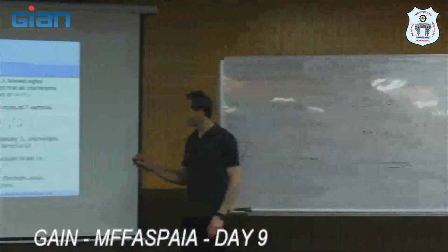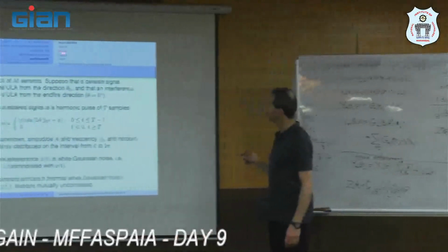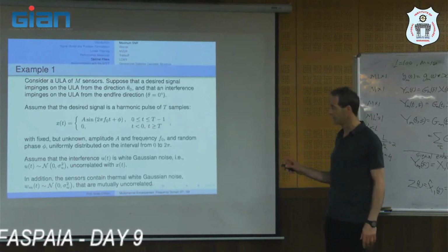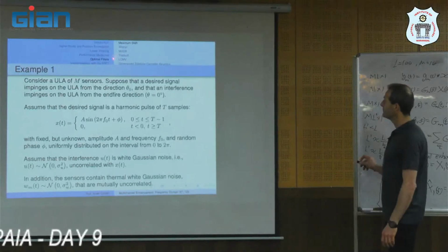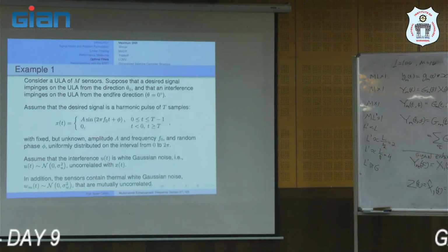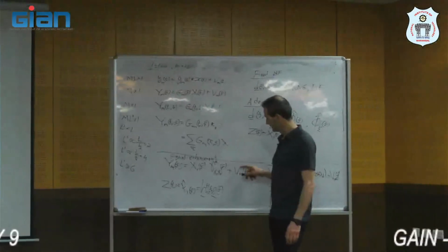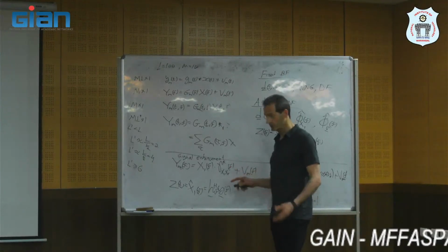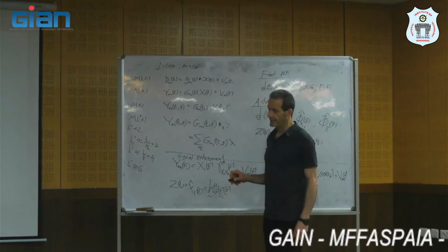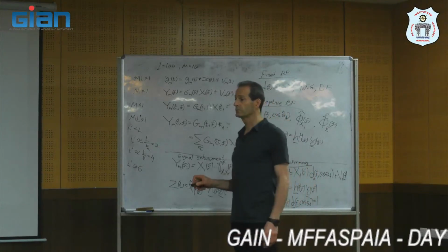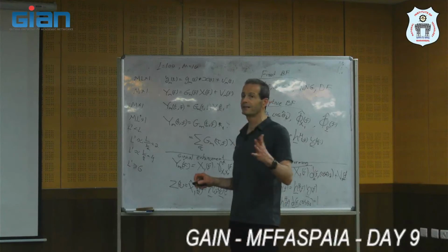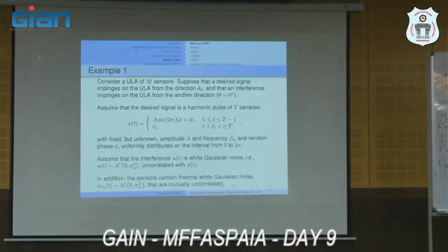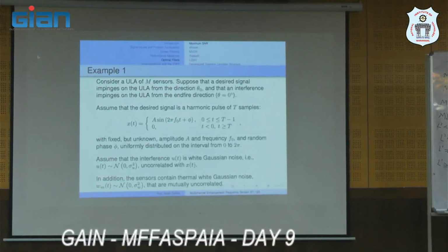So we add an additional constraint to the MVDR. The MVDR has one constraint, distortionless response. For LCMV, we have additional relative transfer functions that are related to the noise sources. And for these noise sources, we want maybe to completely eliminate them. So we add some constraints on interferences in the LCMV.